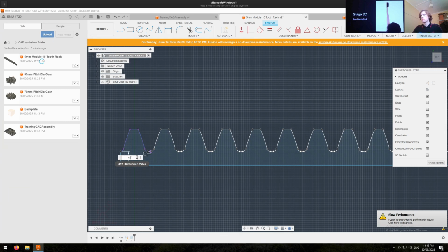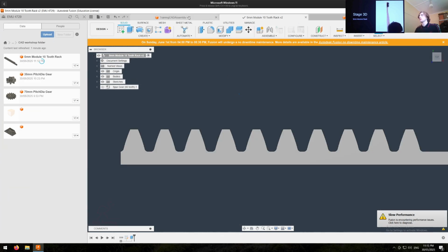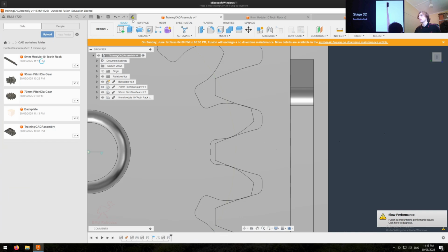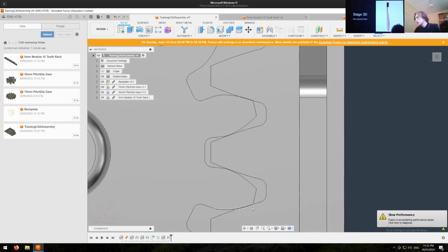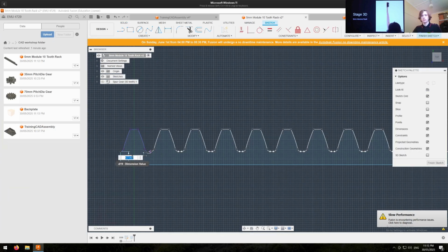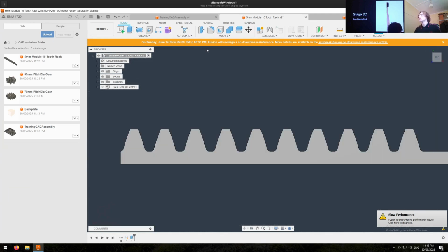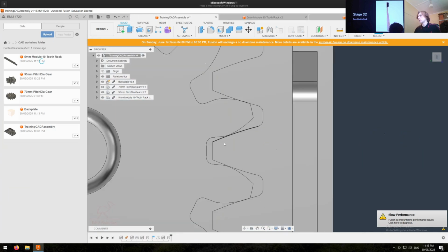Add a little more. Let's say 6.7. Finish sketch. Control S, move over here, update, and there we go. Now they're meshing nicely. I think in reality, you'd still run into some issues because you can see it's binding there. So I decrease it just a little bit further. Let's take it down to 6.5. And one final save, update. And there we go. Now it's running nicer.